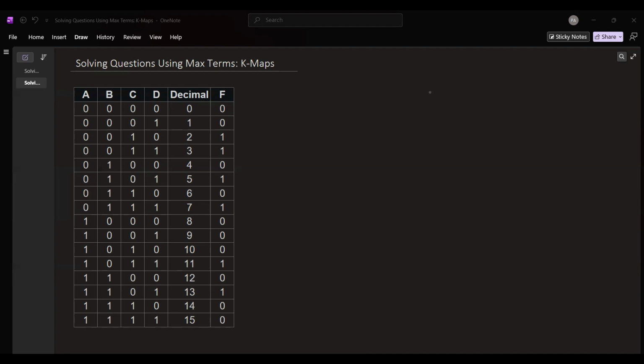The question is same. Logic gate design, circuit design that verifies whether the input number is prime or not. And the number ranges from 0 to 15. So we use 4 bits. All these are explained in the previous video. Please visit there. Now we'll talk here. So we have to find the Maxterms first. And in Maxterms, we know we count the zeros.